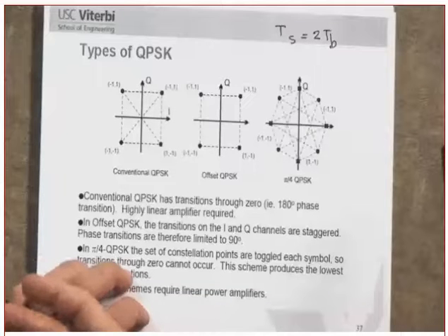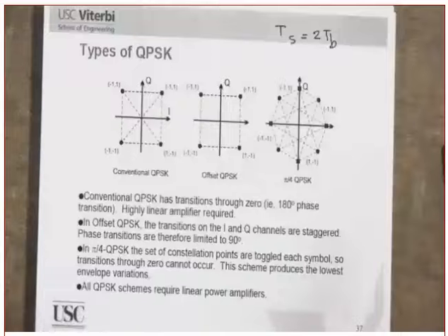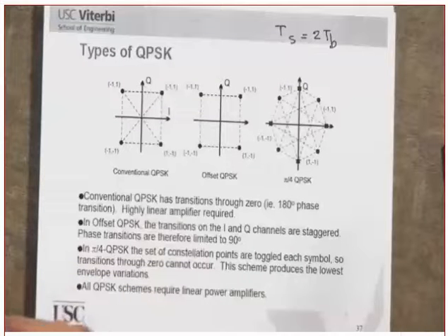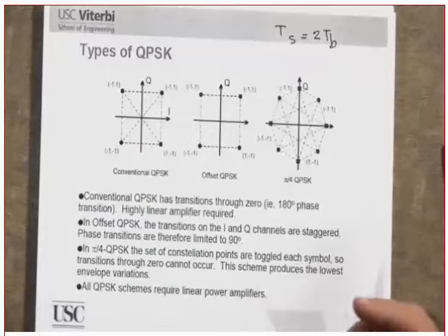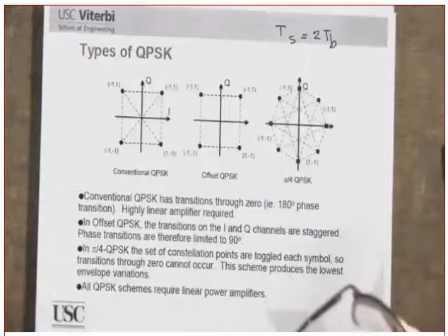Did you get this or not? Always remember, in a power amplifier, which we'll talk about in about 30 minutes, when the power amplifier operates in a nonlinear region, all of these side lobes will show up again. And when they show up again, you are going to cause adjacent channel interference into the adjacent operators. Did you get my point or not? You don't want that.